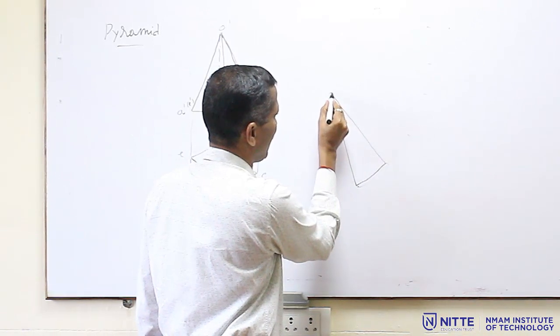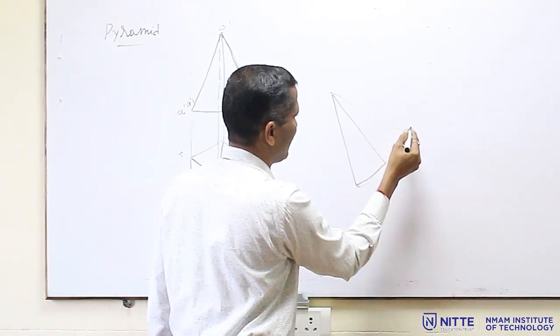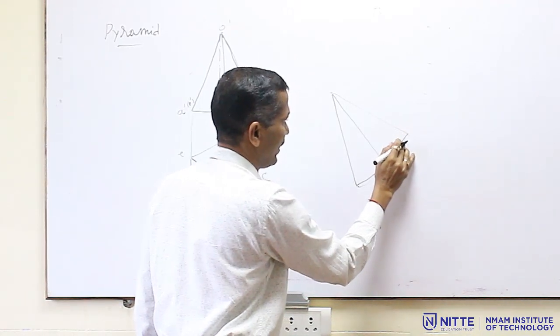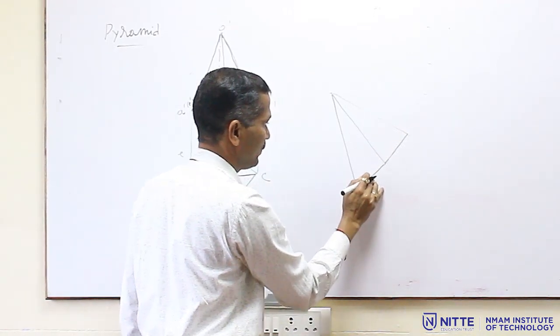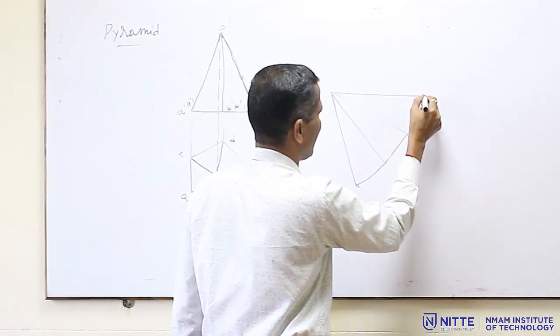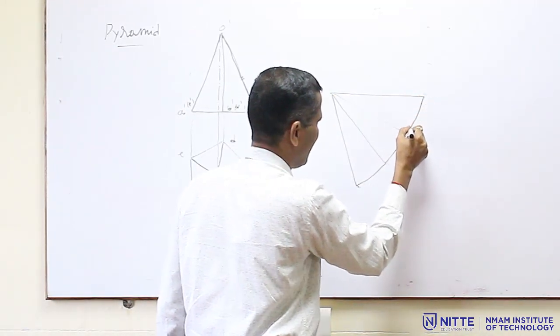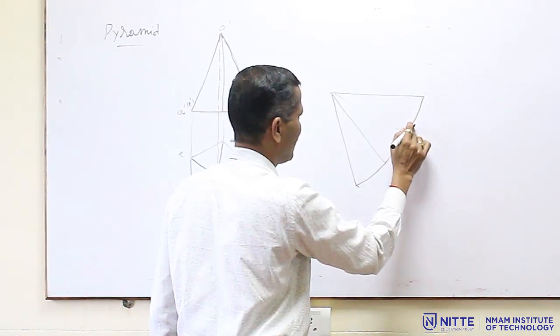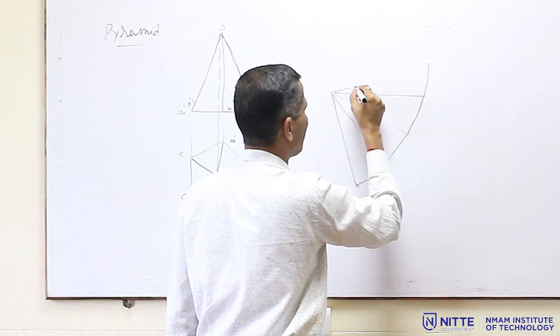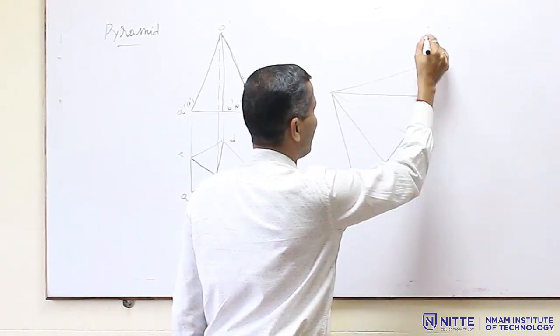Similarly, draw the next radial line and connect it here. Then remove that arc part here also. Then the third segment, you connect here and draw the straight line and remove the arc. Then the fourth one, you connect it like this, and the last point.